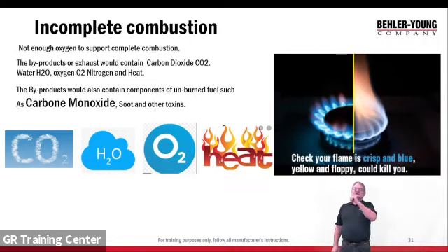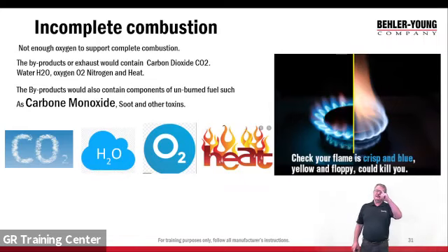But here, you can see the yellow flame. The yellow lazy flame. That's where the carbon monoxide is coming from. What we see there, the blue, that's good. What we see here is not good. When we get that yellow, we have incomplete combustion. There's carbon still coming off that flame. There's a bunch of byproducts coming off that we're not burning off, which are dangerous.